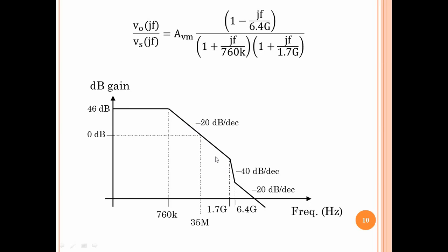So when the second pole and zero appear much after the unity gain frequency, they tend not to affect it. Mathematically, at the unity gain frequency, when the gain is 1, this term is still very small and this term is still very small, and therefore they can be ignored. So we effectively have a single pole transfer function.